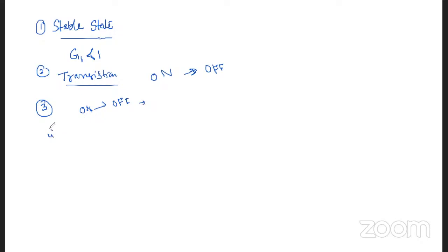Similarly, we have the settling time. The resolving time for a multivibrator is the minimum time interval between two consecutive trigger pulses, and equals the total of the transition time and settling time of the circuit.